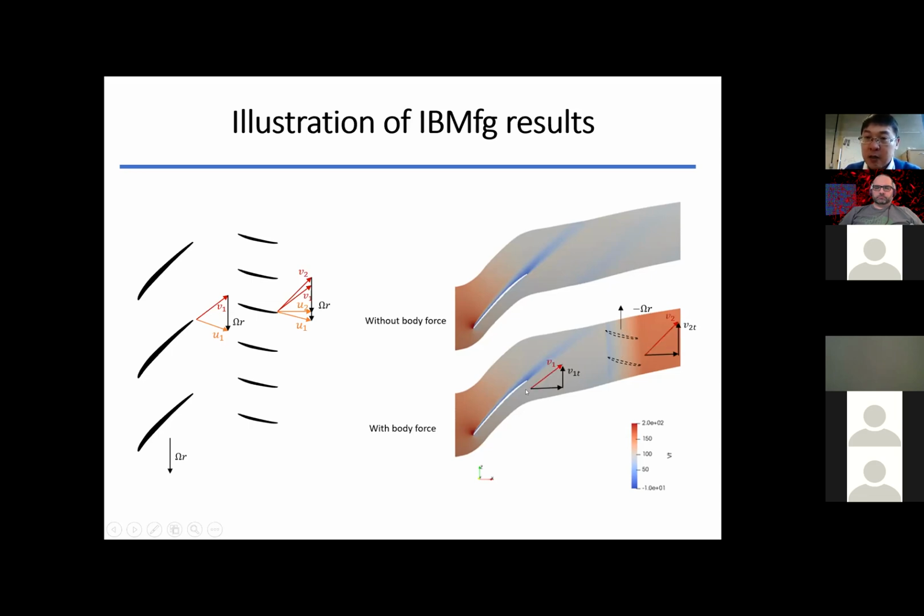If you look at the tangential velocity, I give the contour here. After the stator, the flow is turned into the upward direction, which is desired. So that function tries to turn the flows and give the right pressure rise across the stage.